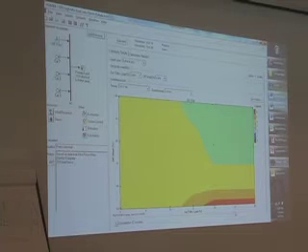But if you set a high, or not even that high, 20-30% minimum load on the diesel, which is not very high actually, that really affects the economics of the wind, and now the operating reserve requirement really matters, because two things are going on here. One is that increasing the minimum load on the diesel makes the diesel less cost effective.